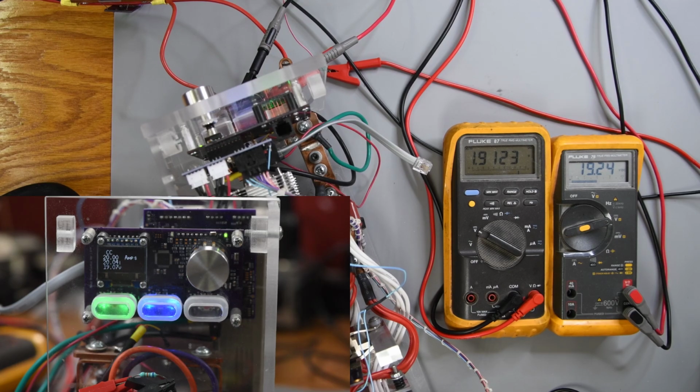I'm at a 20 amp load here, right close to 400 watts. Of course, the meter on the left is reading about 4.25% low for the current. But you can see it corrected at the very start, and then it had to get, well, it's right around 70 milliamps error before it would correct back the other direction. Not great, and if I get the time I may rework this section, but I can live with it just like it is.